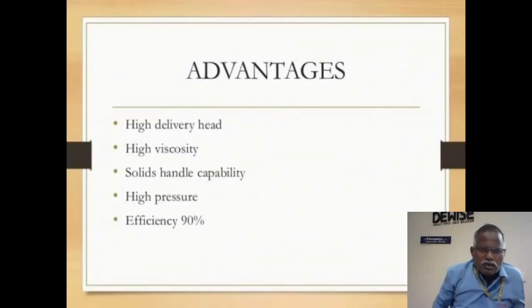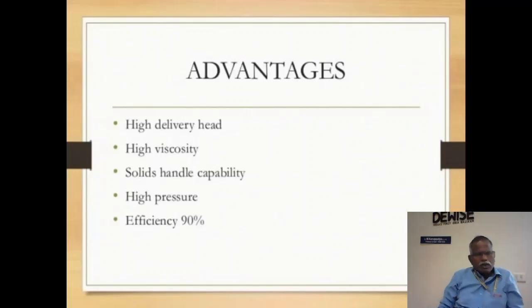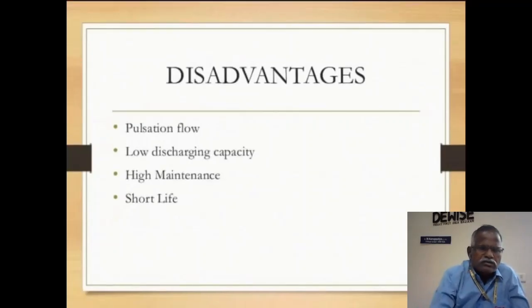Advantages of this pump compared to the centrifugal pump: high delivery head, and high viscosity fluid can be handled by the reciprocating pump. It also has solid handling capability, high pressure, and 90% efficiency.